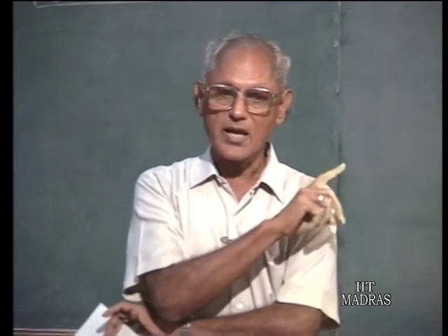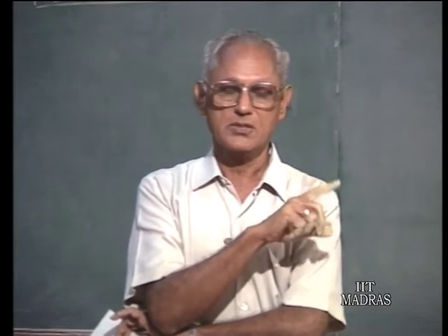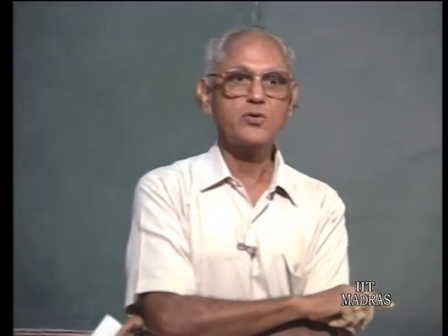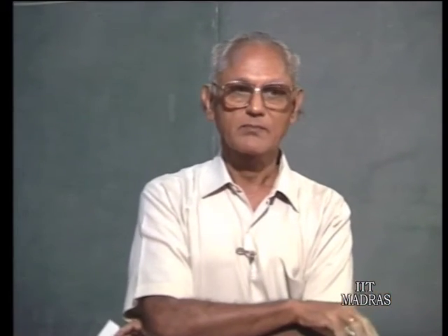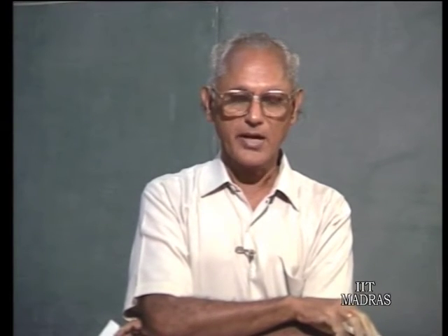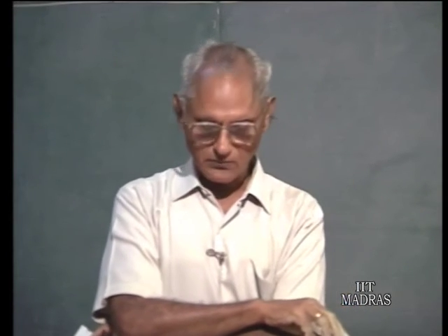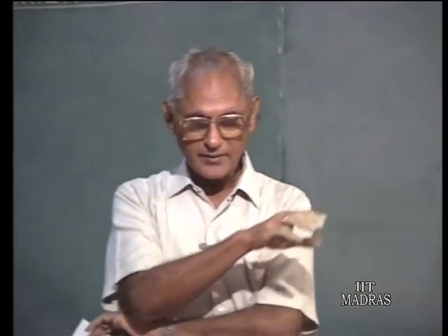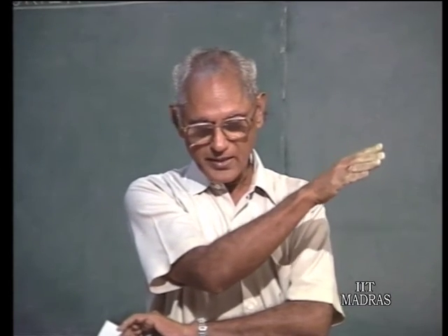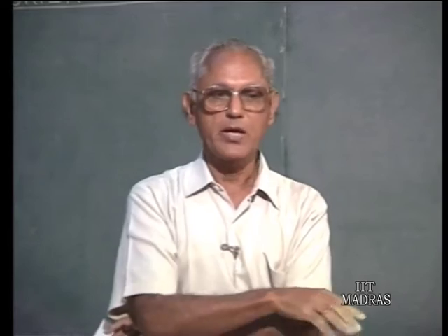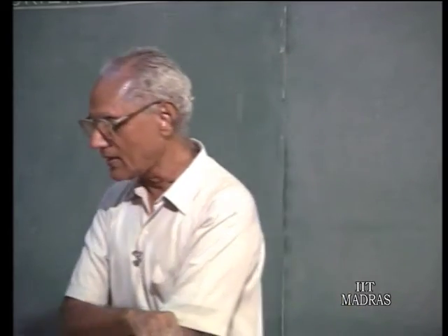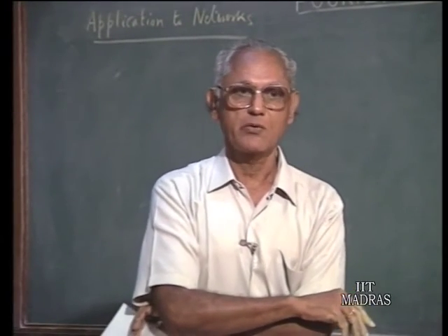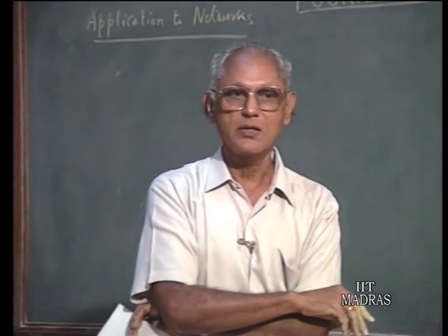Since we are starting the application of these inputs at t equals minus infinity, if the system has a natural response which dies out with time, that is, the natural frequencies have negative real parts, then starting from minus infinity they decay down to 0. When we calculate the response at finite time, particularly from t equals 0 and beyond, all the natural responses would have died out, and what we are dealing with is only the forced response.